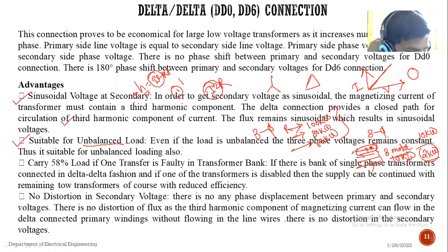Unbalanced loading condition ला delta suitable असेल. Okay, so see, generally in our area, there is a supply line, and if your 3 phase motors are running and if anyone is tapping there, जर एखादा तिथं कोण आकडा टाकत असेल किंवा टॅपिंग करत असेल, somewhat voltage fluctuation will be there. In the voltage we see the bulb flickering or its brightness reduces. So that means unbalance happens in the voltage. Sometimes while anyone is tapping on that line, somewhat light, it may trip also. Okay, trip can also happen.